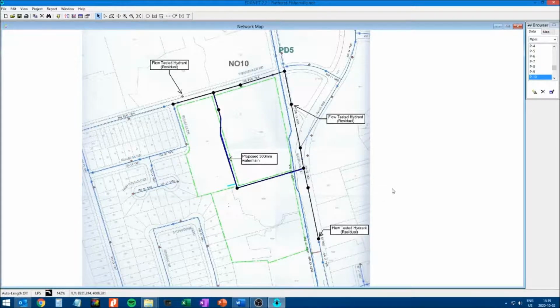Each fire flow test has a pressure measurement at the static condition, meaning 0 flow, and then they typically do one flow, measure the residual pressure, do another flow, and measure the pressure at that flow. Then we take those results and use the NFPA 291 method to estimate the flow available at the hydrant at 20 psi, being the minimum allowable pressure during fire flow.